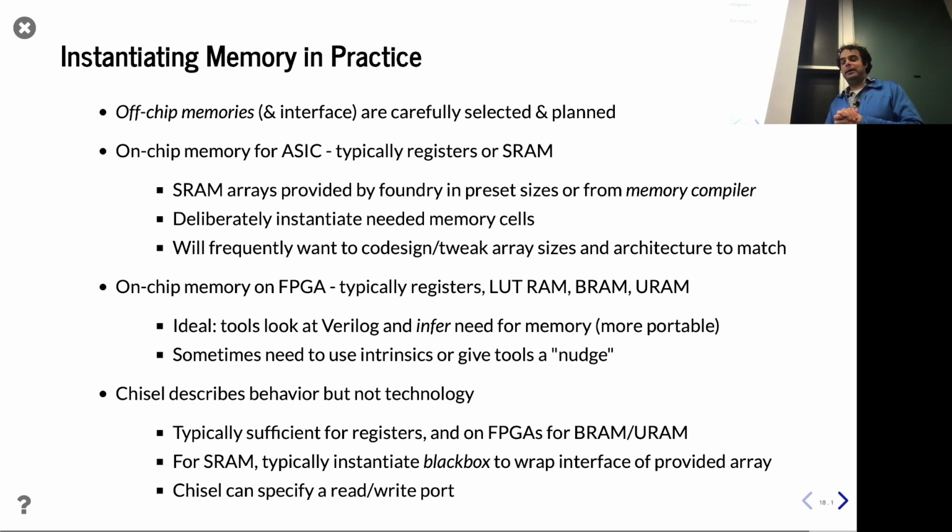Like I said, consider a human working on a large FPGA design. Sometimes there's an optimization choice: well, I have a lot of memories in my design, I should maybe use BRAM. But actually, if there's space available, maybe using LUT RAM is faster. And if there's less space available, you should use BRAM. That decision, that trade-off, that optimization is hard for humans to know, but maybe the tools know that.